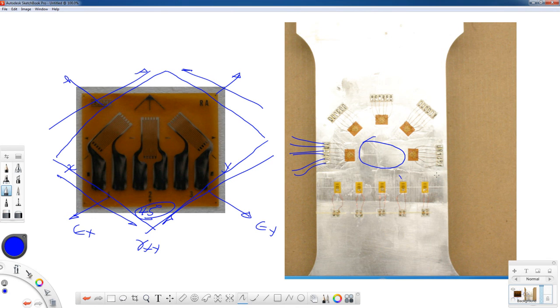So there's a lot of surface preparation that has to go into making sure the gauges stick and behave appropriately in order to take good measurements. There are some other techniques to measure strain called full field strain measurements that include some optical methods.